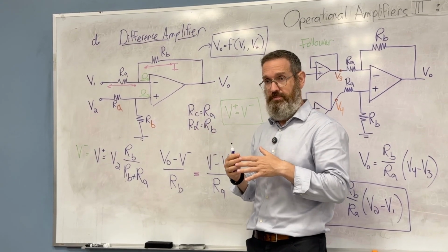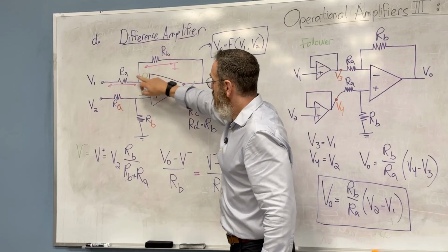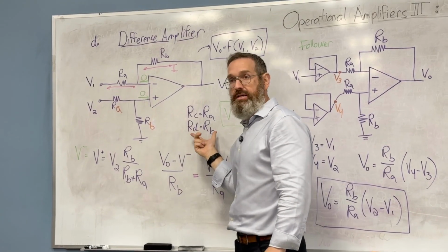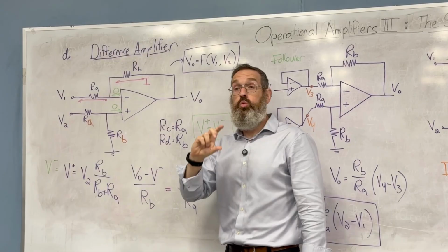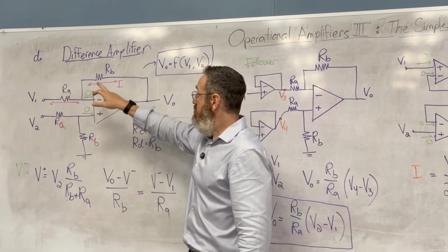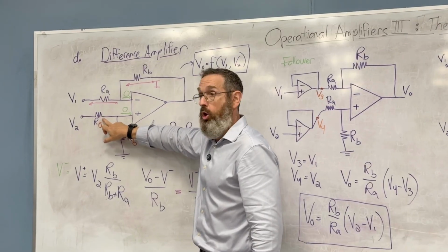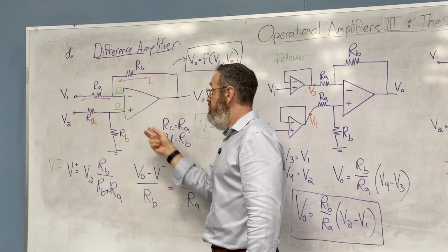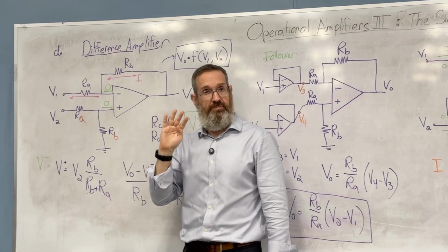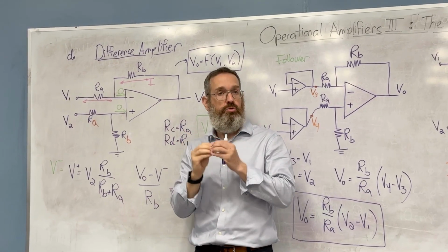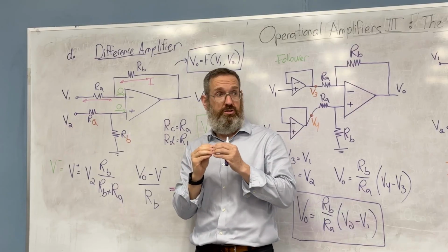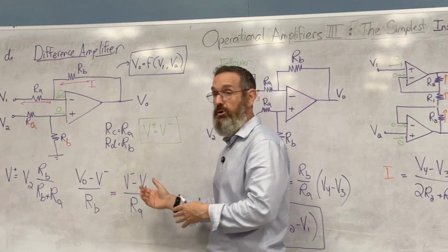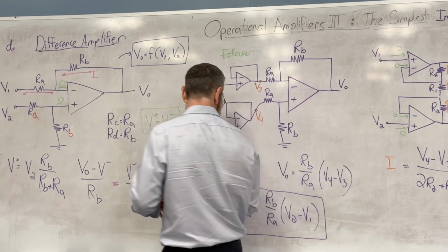But there's another issue. If this is 2 ohm, 1 ohm, 1 ohm, and this is 2.1 ohm, this breaks. And your circuit will not do what it needs to do. If this is 2 ohm, 1 ohm, 1.05 ohms, 2.03 ohms, this is no longer valid. So not only do you need to pick 4 resistors, you have to make sure that they're exactly right. And we'll talk about later what the consequences of them not being right practically, but mathematically it's that you don't get the output we had before, right? Which was the same as this.